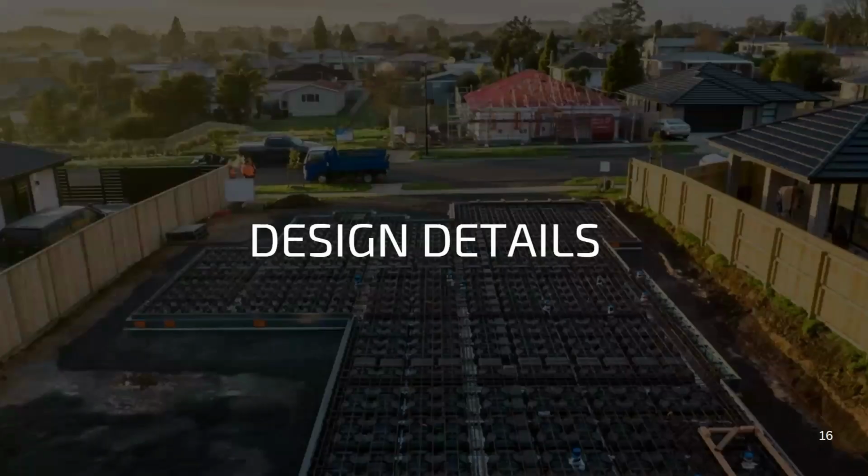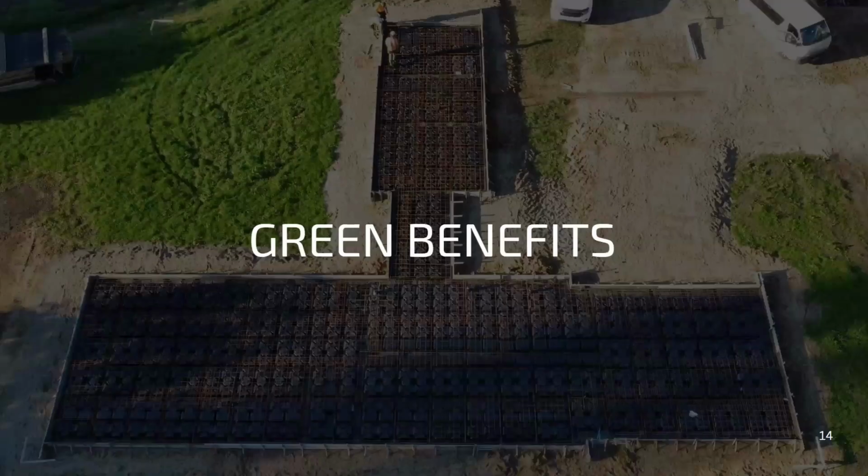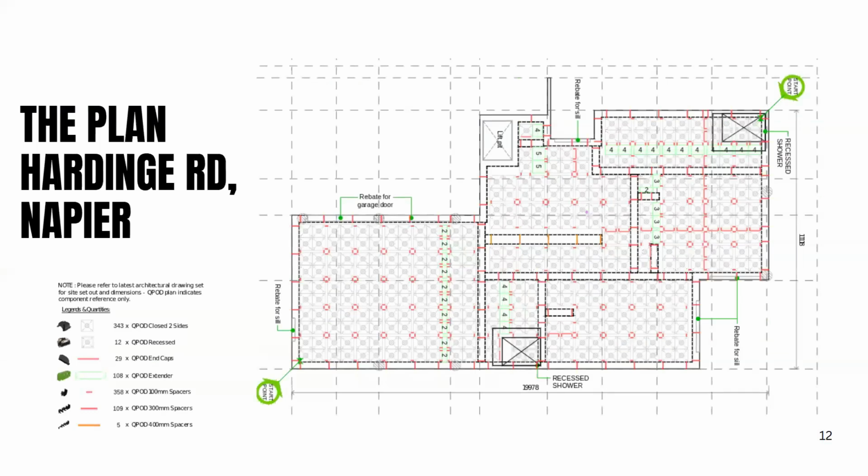Sorry, Peter. Just before we go, we just got a question back on our Harding Road case study there, from Geert. He's wondering, was that done using the continuous system, or was that with the raft system? Yeah, sorry, the screen's not quite showing clear enough there, but that's the raft system. So that was TC3, and most certainly raft in there. I don't think continuous would have cut it for that ground condition. If you look close, you can actually see the rib structures in between the pods. The ribs at 1200 centres, correct. Yep, I've answered that. Phil, have I, Sam? Perfect, yep, thank you.